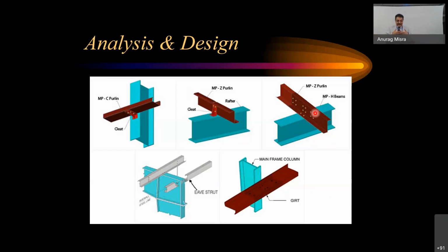good idea that we leave elliptical holes on these purlins, so that the movement of these purlins, because of the temperature variation, is also taken care of, and the additional loads which are going to be created because of the temperature, that gets dissipated.